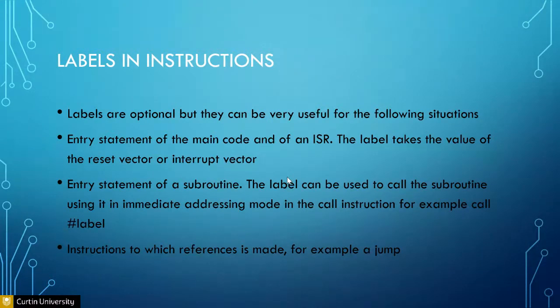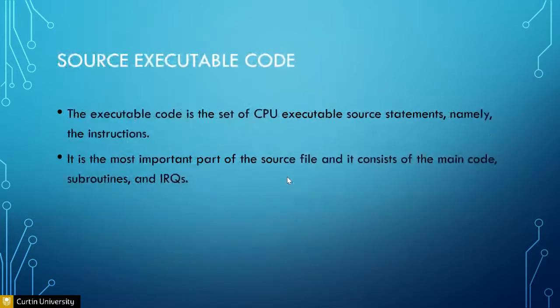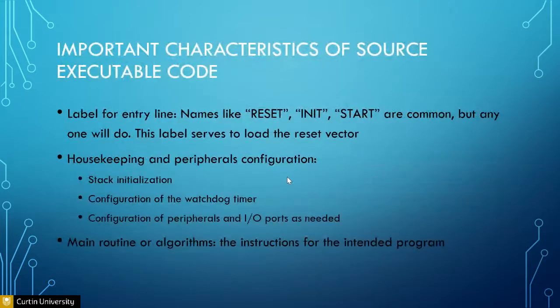All right. Labels allow you to jump from one section of the program to another, because I already told you guys, there's no while, there's no for or if or whatever. There's no such instructions in assembly. That's why you need to use labels. Again, if you know the location of the instruction based on the list file, you can actually do without labels. But labels allow you to jump between different locations without memorizing the location of the instruction.